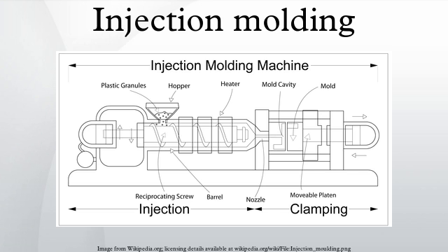Tunnel gates, also known as submarine or mold gates, are located below the parting line or mold surface. An opening is machined into the surface of the mold on the parting line. The molded part is cut from the runner system on ejection from the mold. Ejector pins, also known as knockout pins, are circular pins placed in either half of the mold, which push the finished molded product, or runner system, out of a mold.